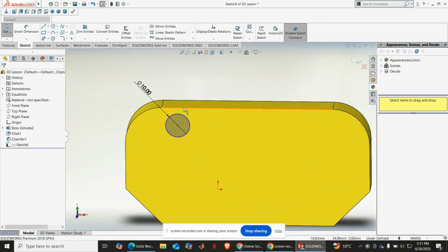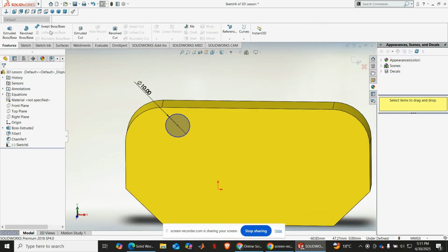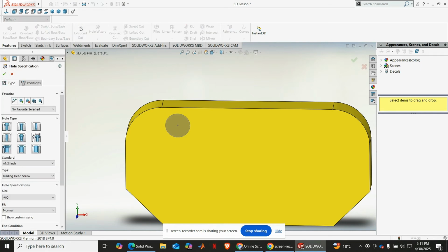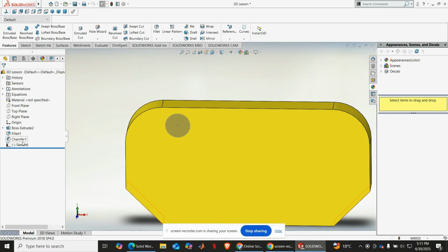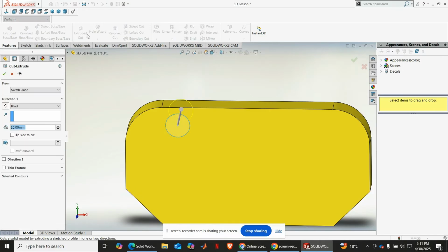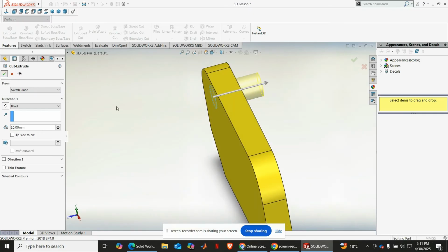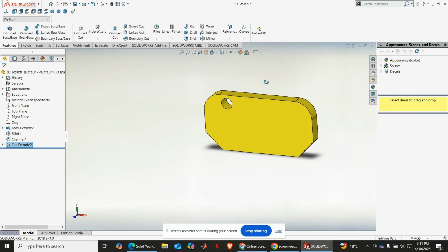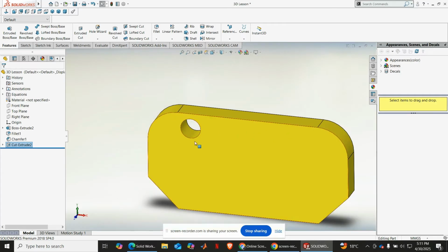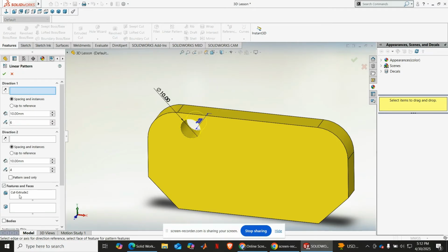Let's say we just want to pattern in the 3D feature. So we go here and say extrude, and then say extrude cut. So we extrude cut that one hole. So you see we have that one hole, but then we need other 4 holes here, linear, right, along X. So we can just come here to linear sketch pattern. So in this arrow, you say linear sketch pattern, and then here, you select the feature. So this feature here is selected automatically.